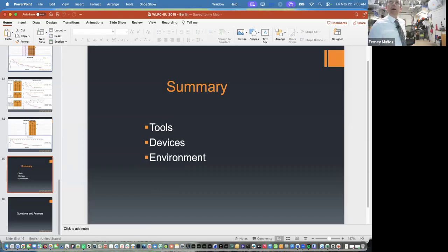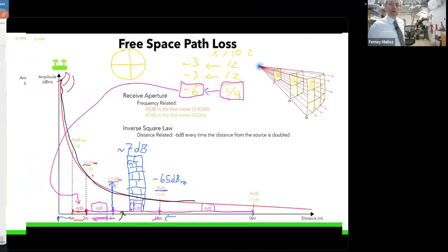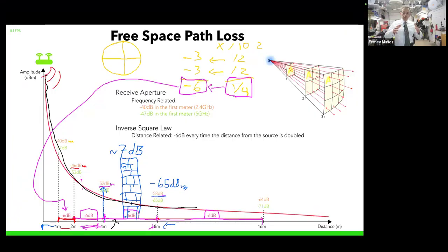Because when we are talking about attenuation, these waves through free space is one thing. But as I showed you in one of the first sessions, on a football field, an open field, I was getting a strong signal, weaker signal, really weak, and then really strong again. Why? That defies the laws of physics. Physics says that as you go away, this energy becomes weaker. And then it was getting stronger because we had reflections off the bleachers in that stadium. So we were just getting bounces of waves.